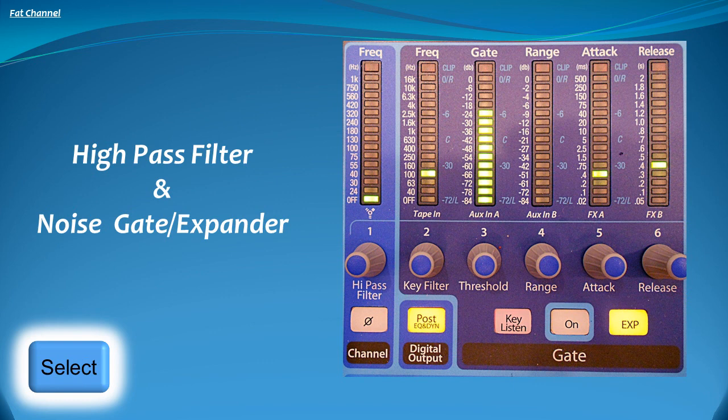There are 3 control buttons at the bottom of the noise gate section. Of special note is the expander function, labeled the EXP button. An expander is a more sophisticated type of gate and produces a much smoother, more natural sounding effect. For most situations at LifeGate, we will be using the expander function. The on button is used to either enable or disable the gate. When disabled, none of the gate functions are active, even though the settings can be changed.